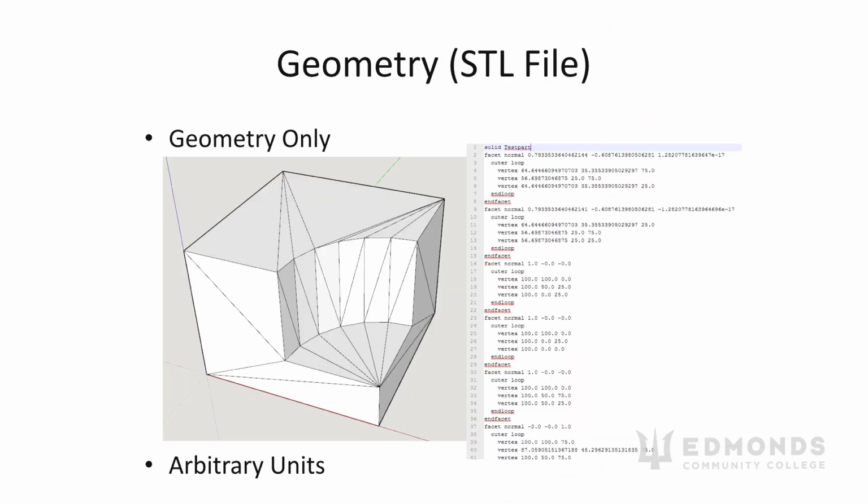The next step in the additive manufacturing design process is that we need to turn our geometry into an STL file. STL is currently the standard for additive manufacturing, may not always be, but it's usually used as something of a backronym which describes its behavior. Standard triangle language or standard tessellation language are a couple of examples, but we would call it stereolithography frequently.